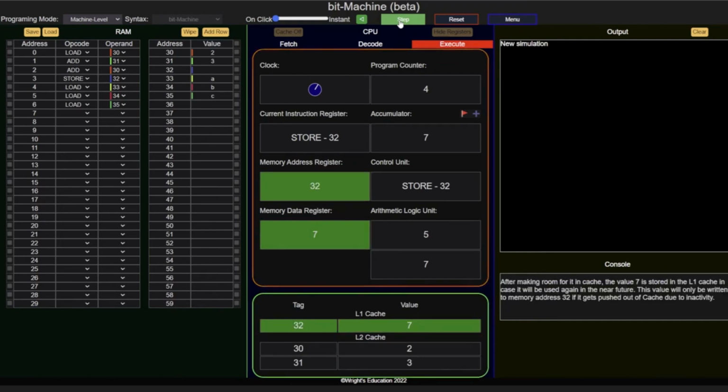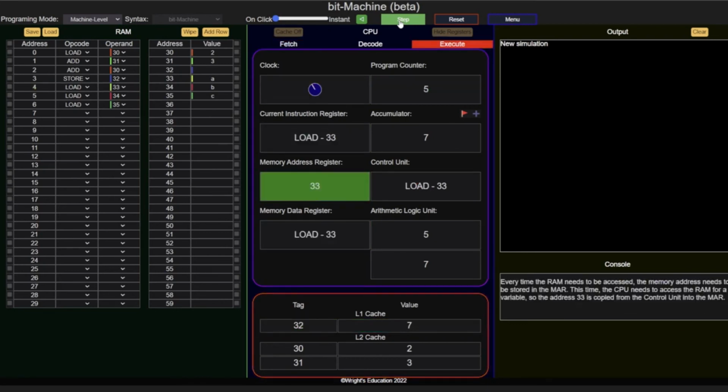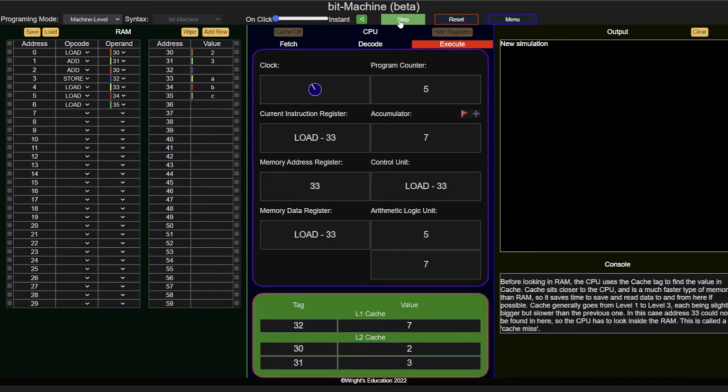SUB stands for subtract and it will take the value at the memory address and move it to the buffer register, known as reg B or register B. During program execution, the contents of reg B will be subtracted from the content of reg A and it will be indicated in the sum register. The value from the sum will be moved to reg A where it can be used later in the program.